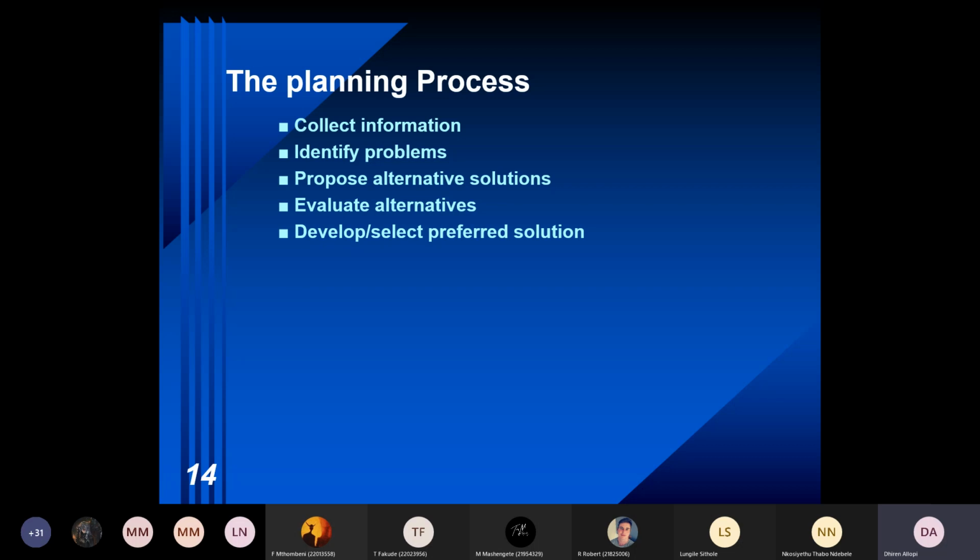So you can see from there, when it comes to an intersection, certainly one needs to have some sort of system to control your traffic at the intersection. They are at the same level, at grade. So it could be via a stop sign, a yield sign, a traffic signal, okay? Whilst with an interchange, because your roads are crossing at different levels, at different grades, you can maintain uniformity in speed, you can maintain the capacity on the road.